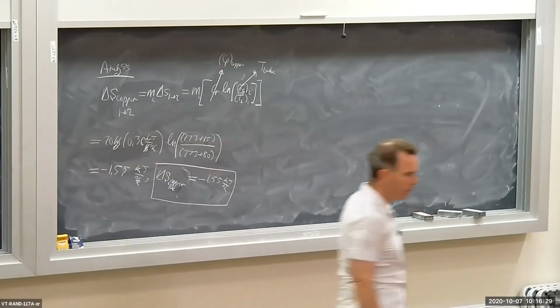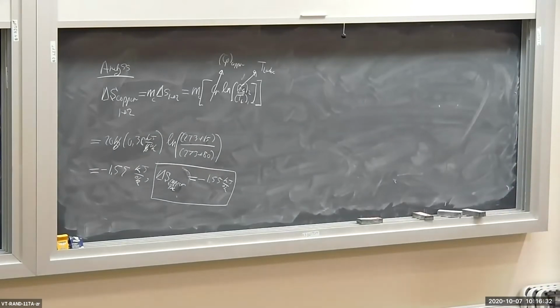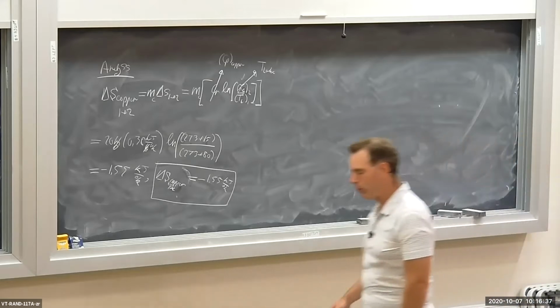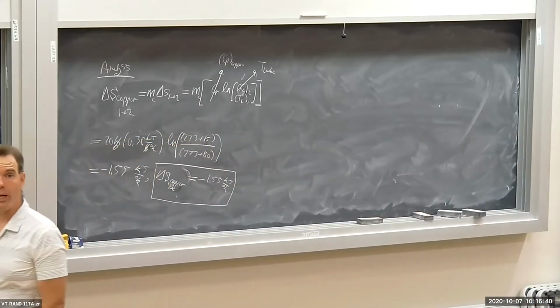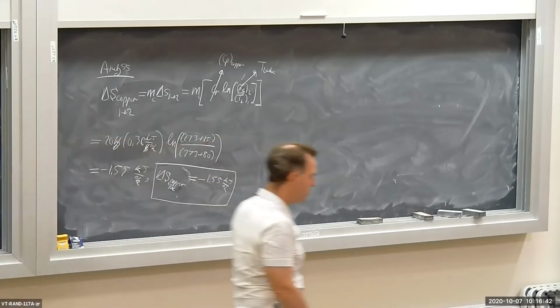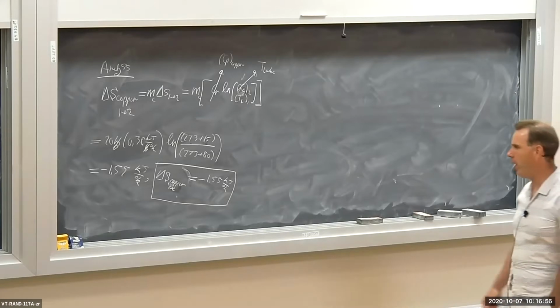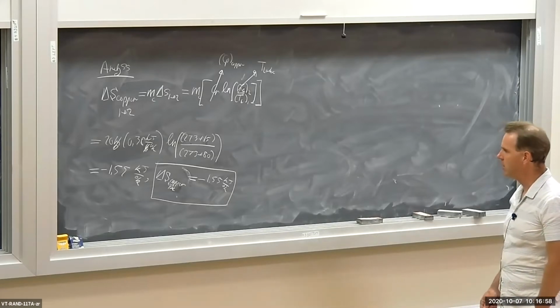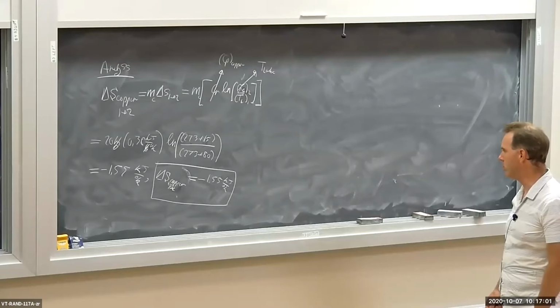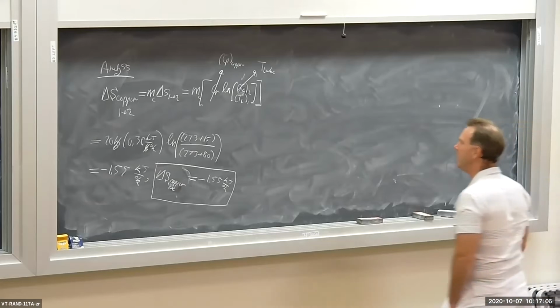Usually, holding pressure constant, as temperature goes up, entropy goes up. Why is that true? Because to raise the temperature of some system, you usually have to add heat, and when you add heat, you add entropy. Or you're having to do work on it, and often that's shaft work or electric work, which is also irreversible. Okay? All right, so the copper entropy went down.